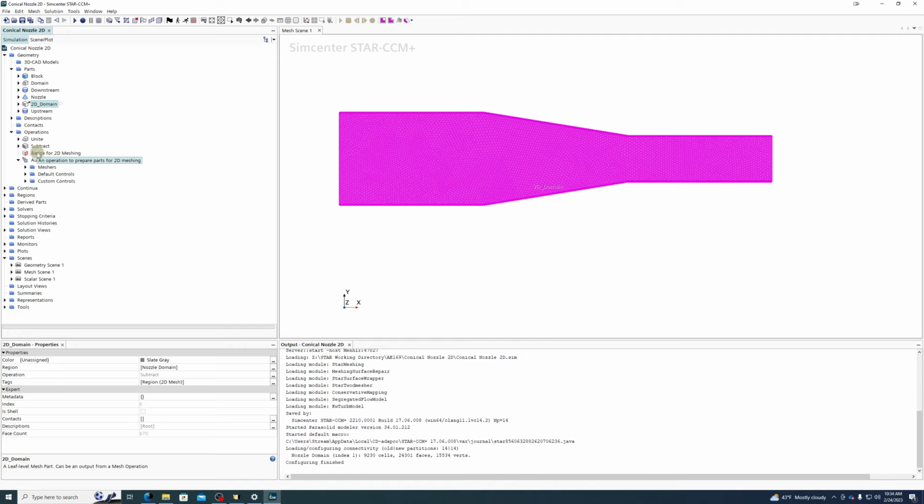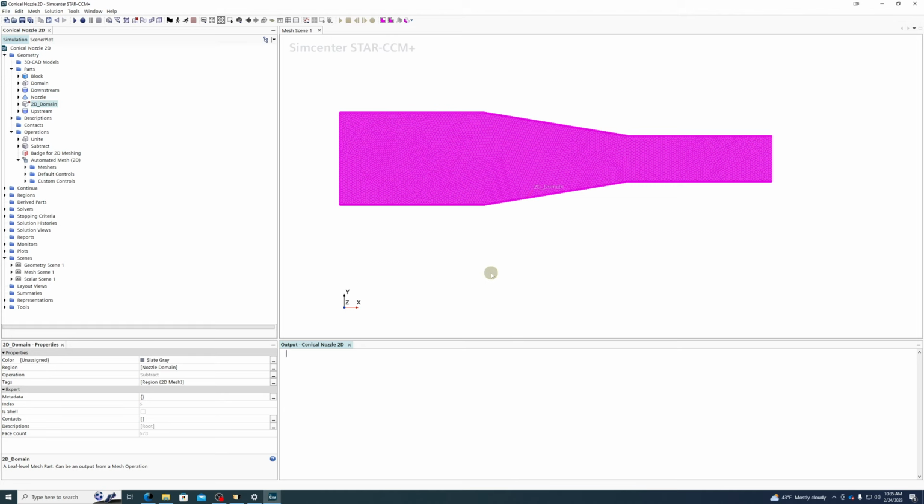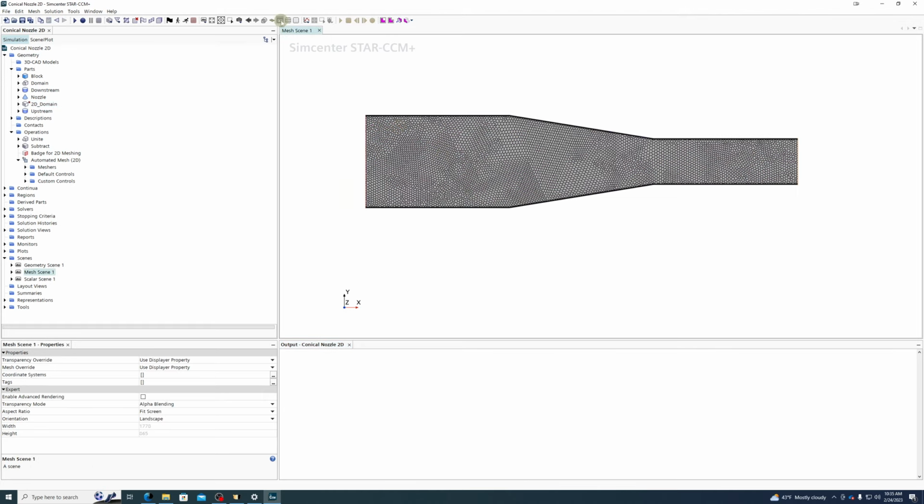So when we're setting up for 2D meshing, there's a couple of important things. With 3D meshing, this step isn't needed, but for 2D meshing, it is absolutely required. You must have the plane, the two-dimensional plane that you wish to simulate, parallel to the XY plane and located at z equals 0. So if I go up here to this measure tool and I measure any 2 points on here, you'll see that it spits out exactly 0 for z. That is, this plane that we're looking at here exists at z equals 0 and is parallel to the xy plane. The xy plane is what it is simulating.